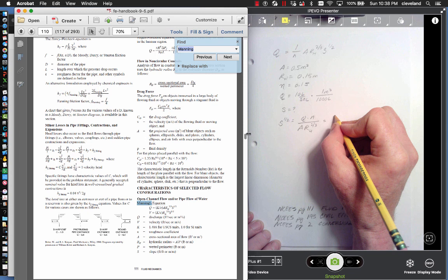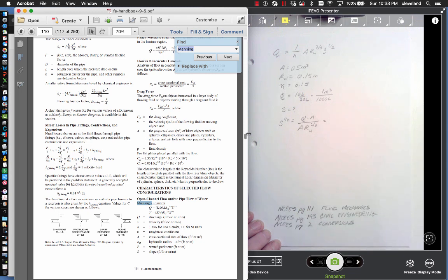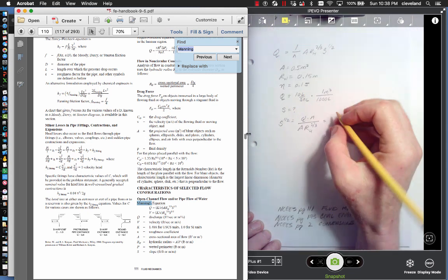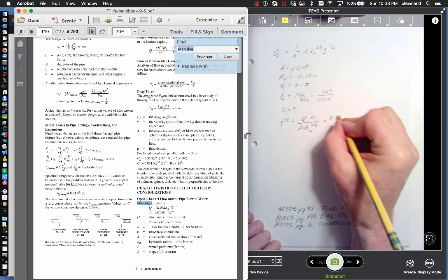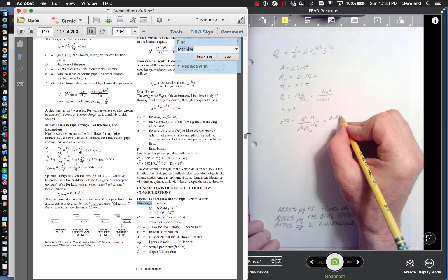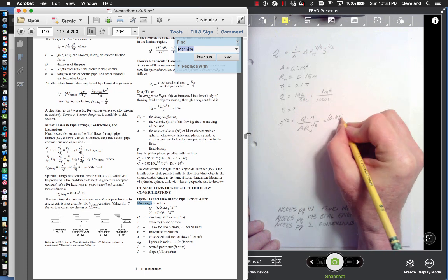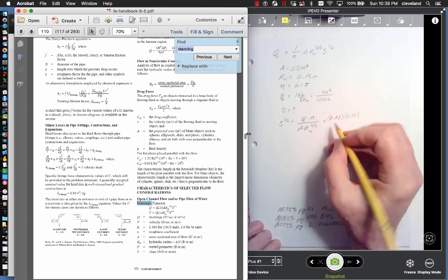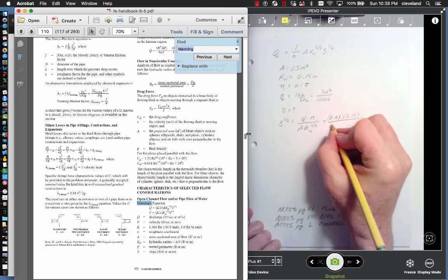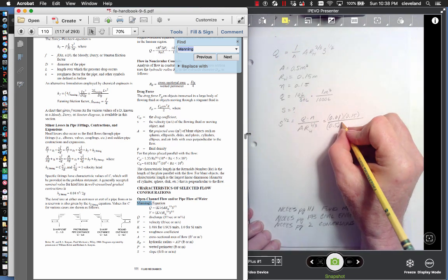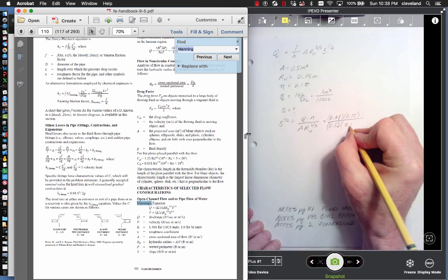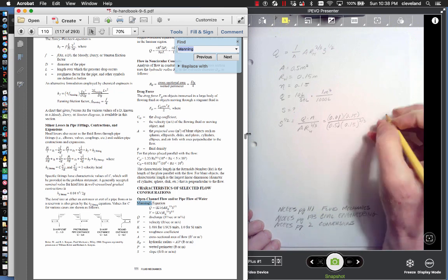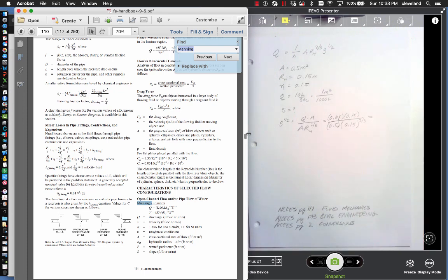This equals, see, 10 over 1,000 is 1 in 100. 0.01 meters cubed per second times 0.15, the roughness coefficient, divided by 0.5 meters squared, the area, and 0.15 to the 2/3 power. We'll first perform that indicated arithmetic, and then we'll square the result to recover the slope.